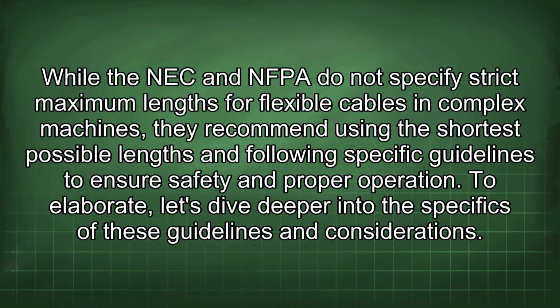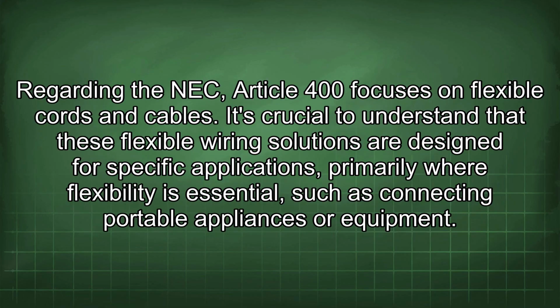While the NEC and NFPA do not specify strict maximum lengths for flexible cables in complex machines, they recommend using the shortest possible lengths and following specific guidelines to ensure safety and proper operation. To elaborate, let's dive deeper into the specifics of these guidelines and considerations. Regarding the NEC, Article 400 focuses on flexible cords and cables.